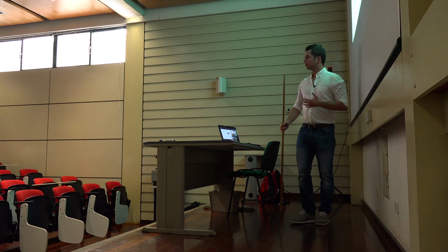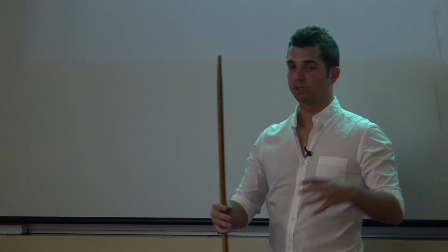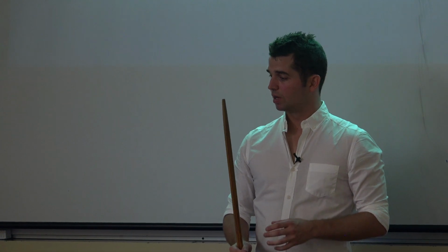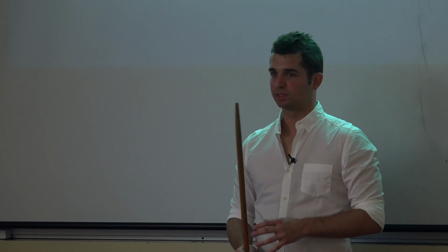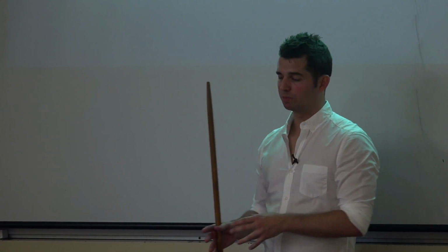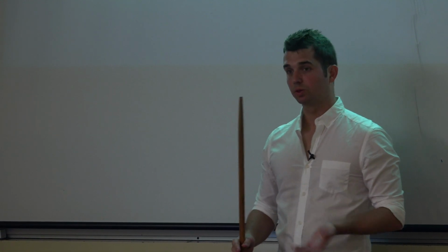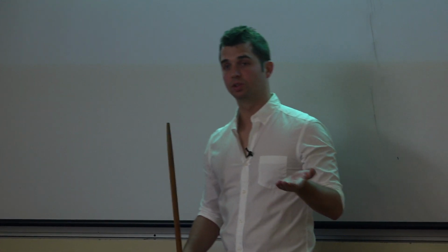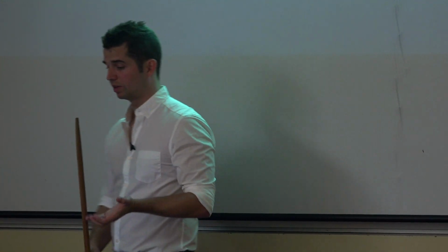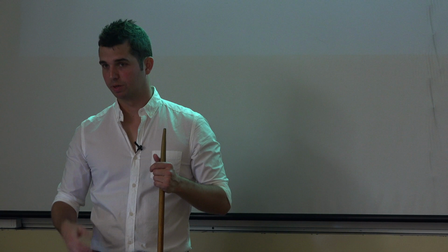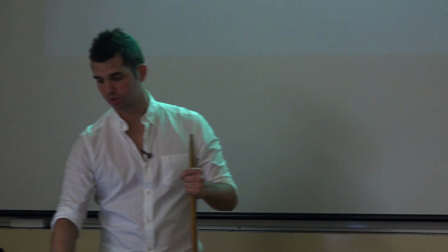So you want faster circuits, right? But you're decreasing the size of the circuits. Although the capacitances, I prefer not to speak about them because the way that they scale is very complex. The resistance goes up. So this does not help with increasing the speed of circuits.